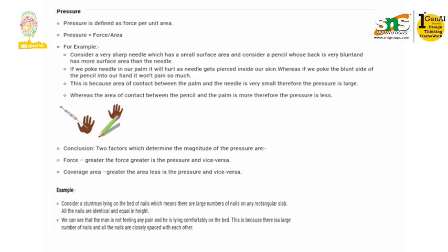Also the area of the heel: the heel is circular in shape, as already given. The area of a circle is pi r squared, so pi into 0.005 whole squared. On calculating we'll get the answer. They are also asking us to calculate the pressure, for which we need two quantities. One is force. Force is equal to mass into acceleration due to gravity, so 50 into 9.8 gives you 490 Newton. Substituting into pressure equals force by area, we get 6.24 into 10 to the power 6 Newton per meter squared. Okay, so that is the answer. Thank you.